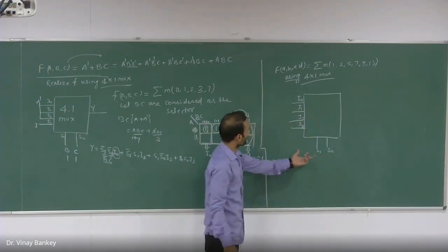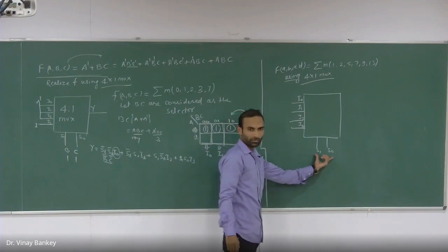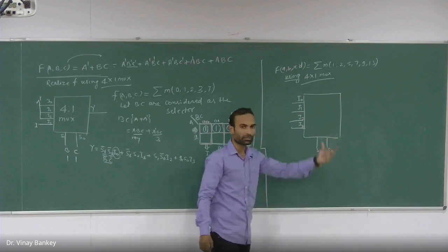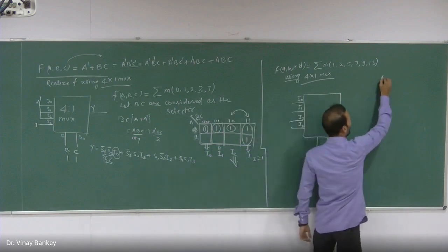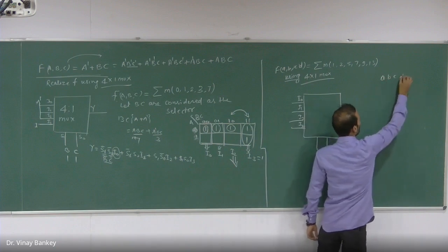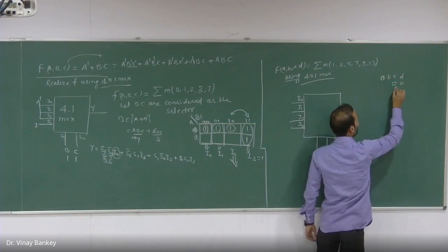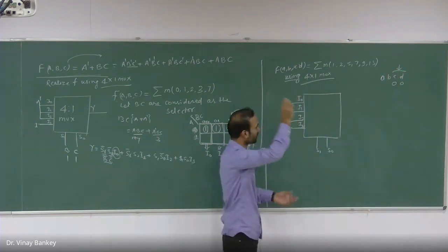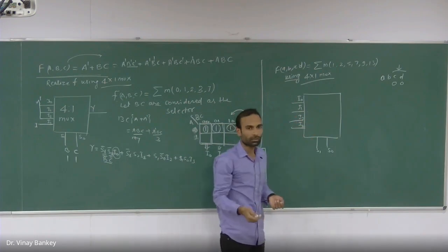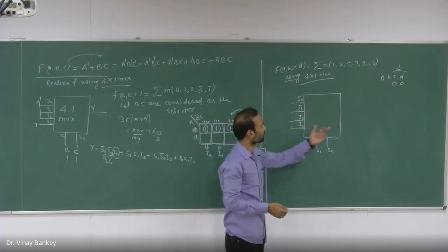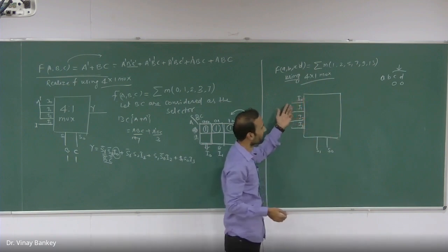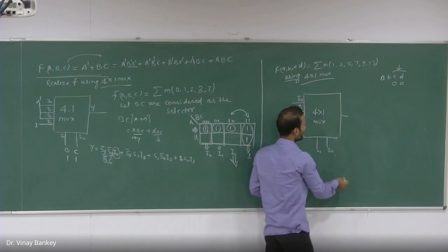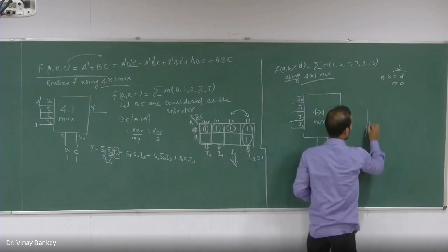So what is the first procedure? You need to assign these selection lines. And always remember this selection line should be your LSB side. Okay, it's A, B, C, D. This CD I consider as a selection lines, because in this way the question will be simple. Otherwise, you will face the problem when you try to obtain what should be connected at these inputs. Okay, now this is my 4 cross 1 mux, and these are the minterms given.